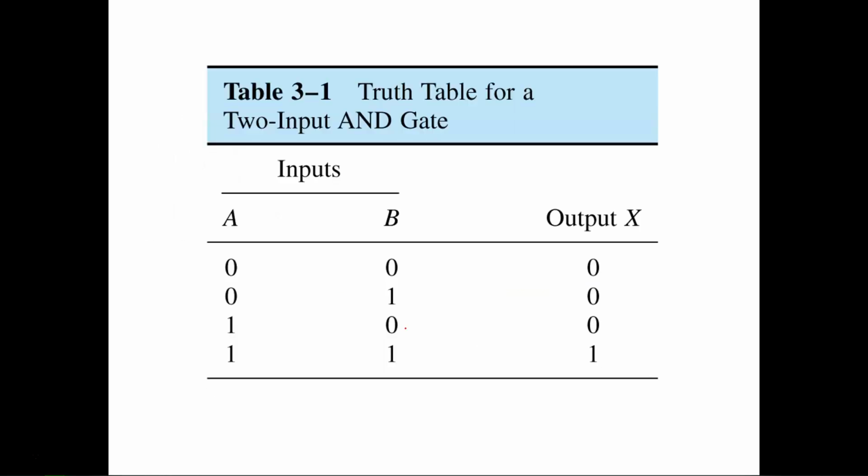So here's the truth table. So when do I get an output? I only get an output when I've got both inputs active. Otherwise, I will not get an output. Makes sense since it's AND logic, right? A and B have to be in sync before you get X. If you remember nothing else, remember that.